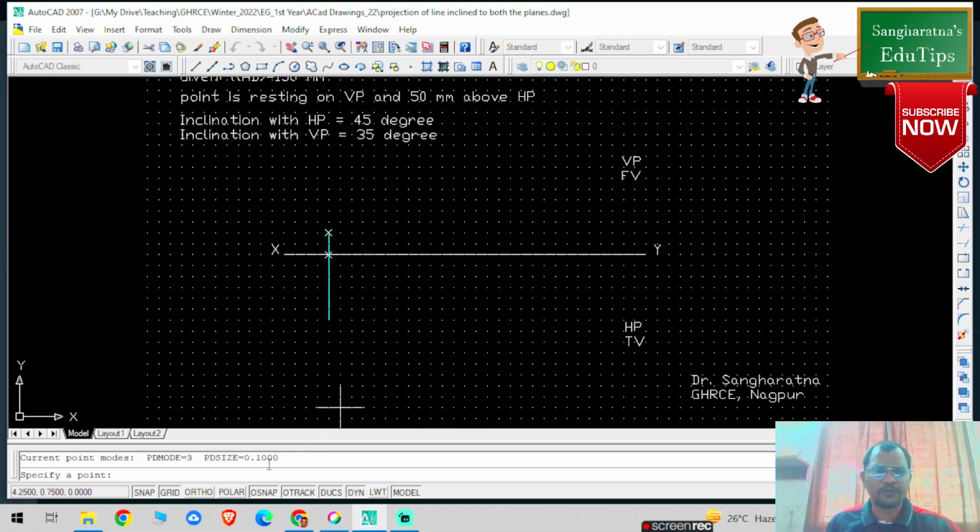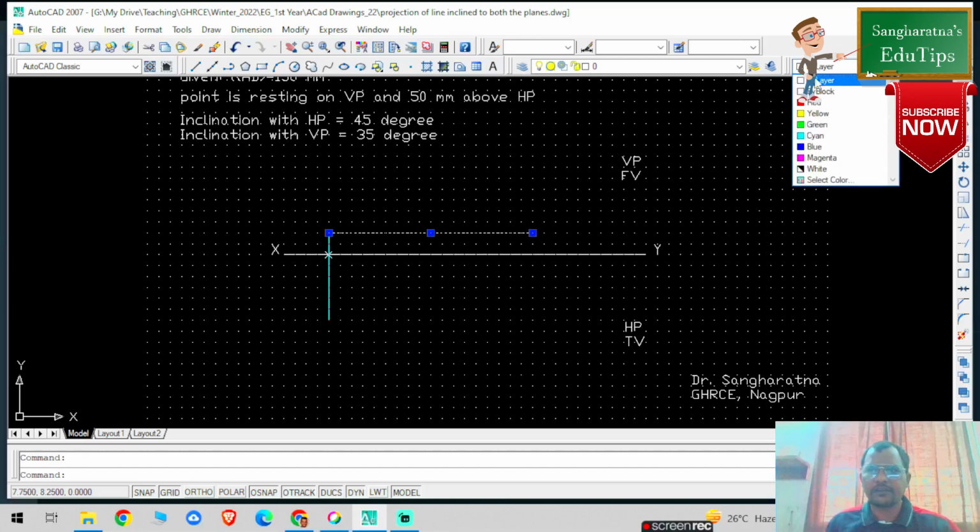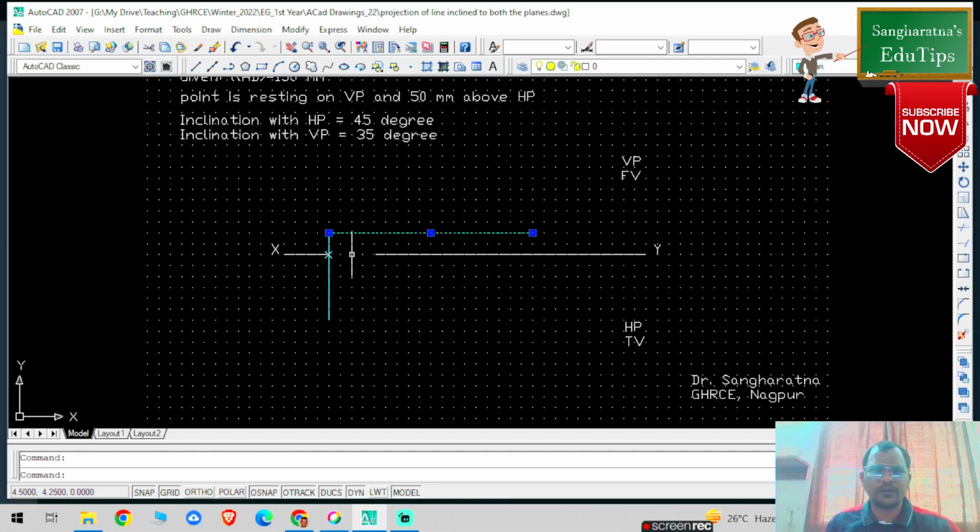Immediately I'm going to draw one projection line from this particular point horizontally. Then pressing escape, and converting into cyan color. If I draw a projection on XY, it's not visible, so no issues. And I'm going to give its naming with the text command. Here I'm writing height spacing 0.2 and rotation angle 0.